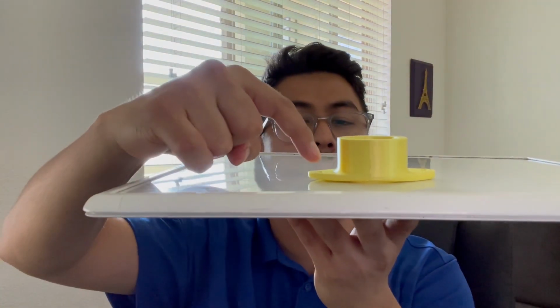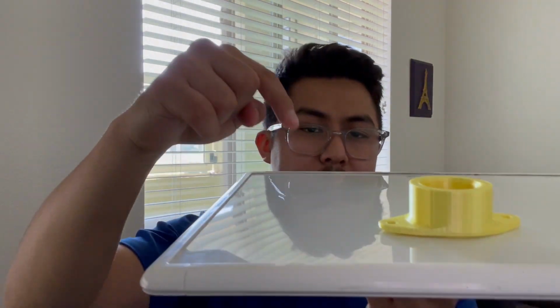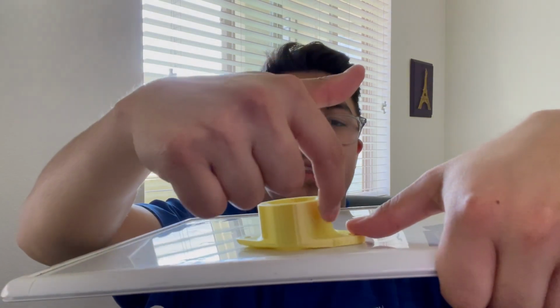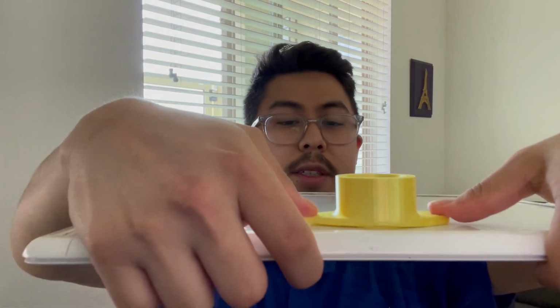And so if you put this on the surface, you'll notice that if I try to mount this to the interfacing part, and I introduce some clamping force here, so this gets mounted here, here, and now what I'm doing is introducing some stress at this radius here. So again, it can pass inspection, everything can fit together, but now you introduce preload that could have been avoided if you had a flatness tolerance on this surface.